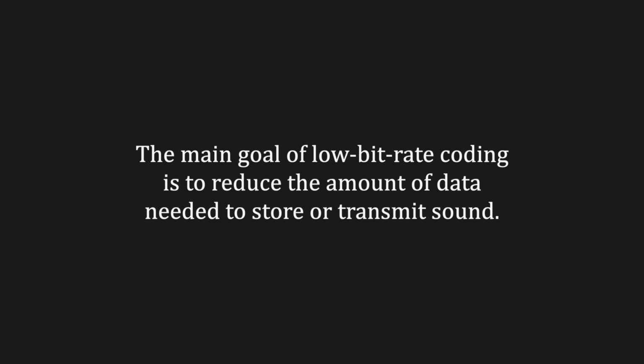and increases quantization noise. A better solution uses psychoacoustics, keeping the same sampling rate but adjusting the word length dynamically based on what the ear can hear. This method takes into account masking and other hearing factors to hide noise beneath the threshold of audibility. By using psychoacoustic principles, the codec can make added noise practically inaudible.